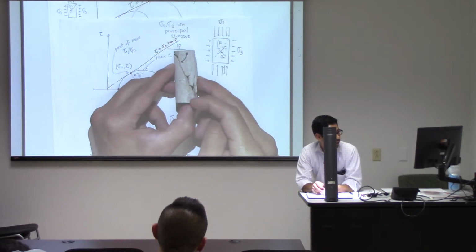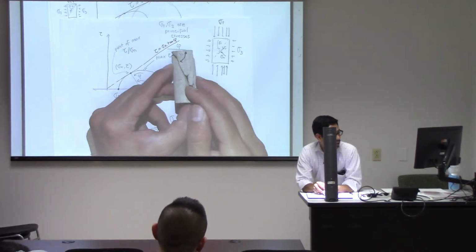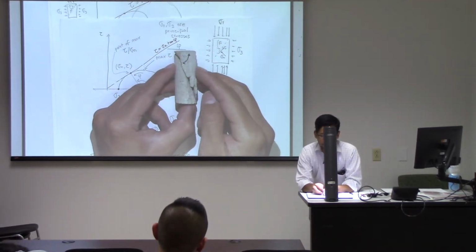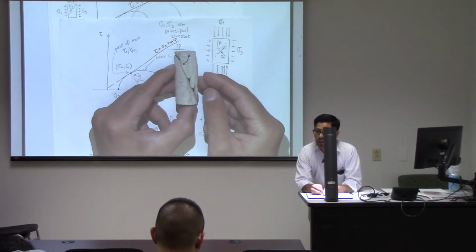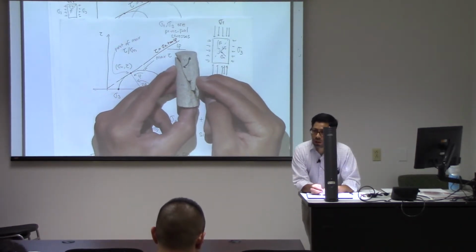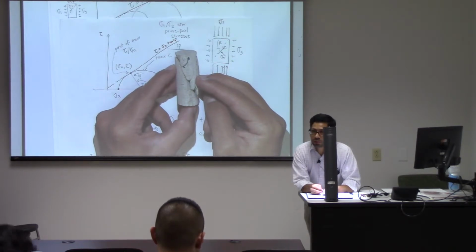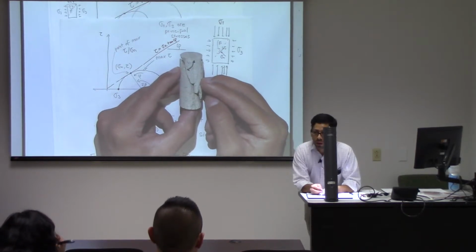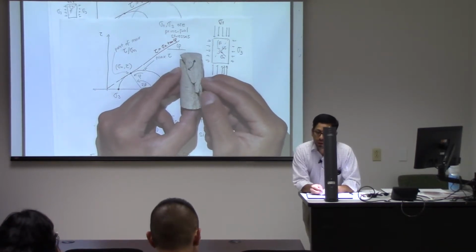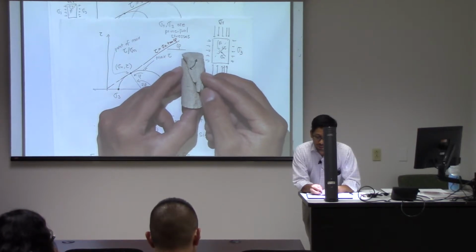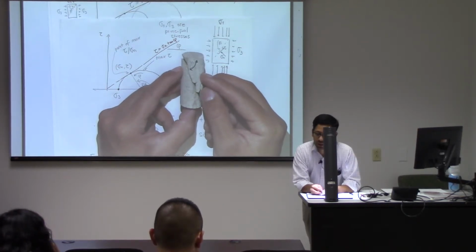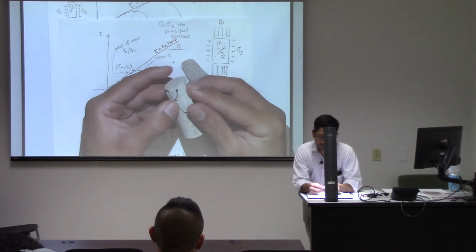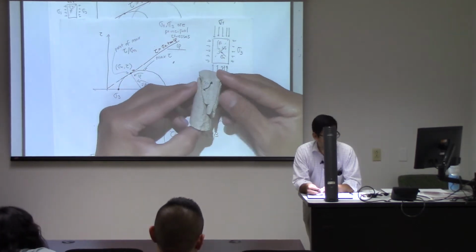This is a shear fracture, and the orientation of that fracture depends on the friction coefficient of the rock, and it's always going to be a steep angle. Remember this very well, because we're going to use it a lot when we look at faults, because faults follow exactly the same principle. So if you know the friction angle, you know what the shear fracture orientation is going to be. The rock is always going to fail in the plane of the maximum shear to normal stress ratio.